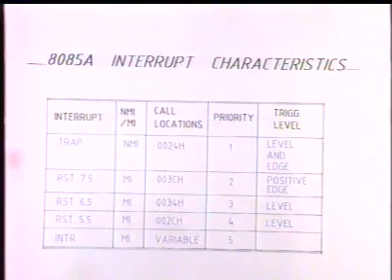So now we see that 8085A has 5 external interrupts. The first one is TRAP, which is a non-maskable interrupt, and the remaining 4 are maskable interrupts, of which 3 are RST 7.5, 6.5, and 5.5, and the fourth one is INTR.